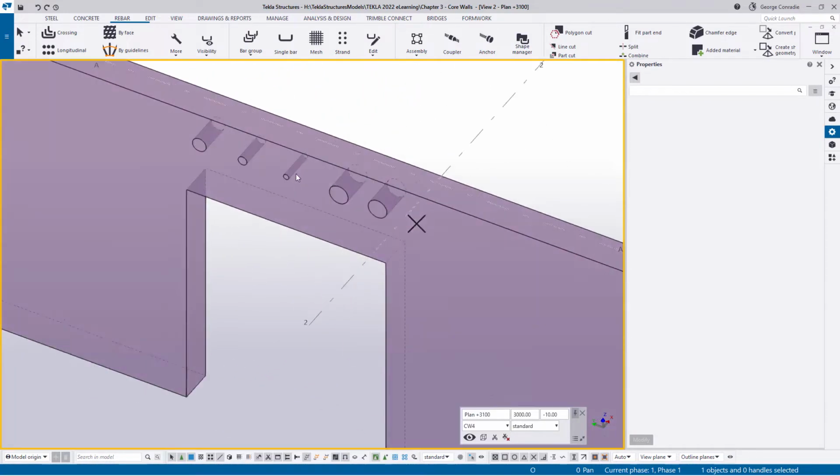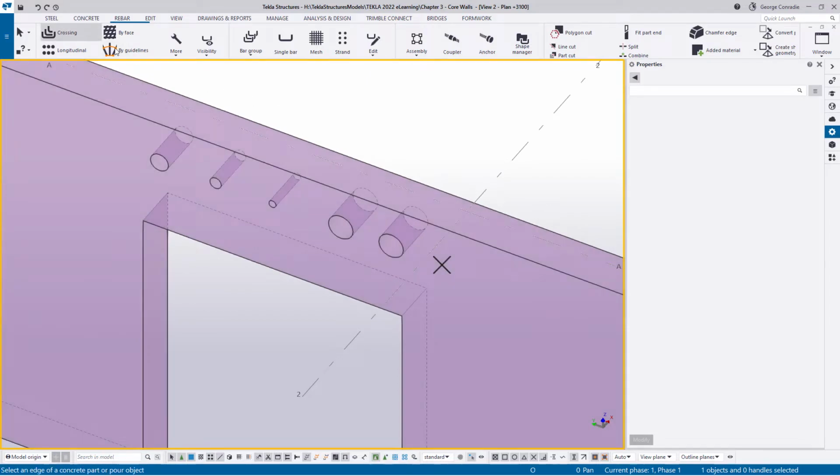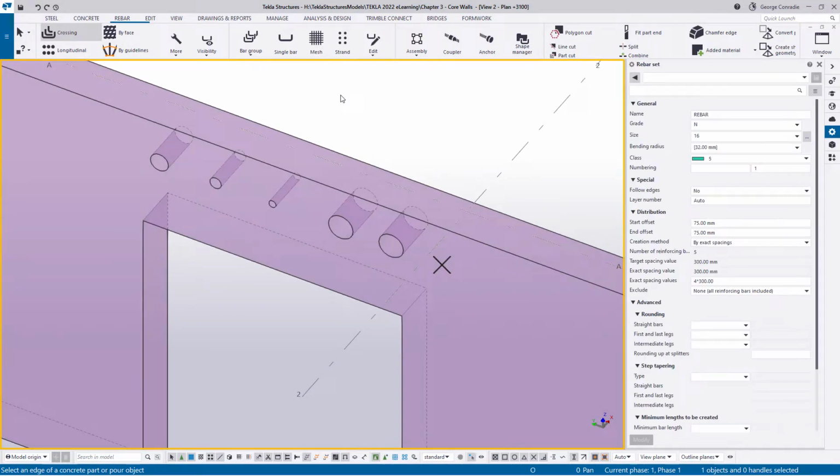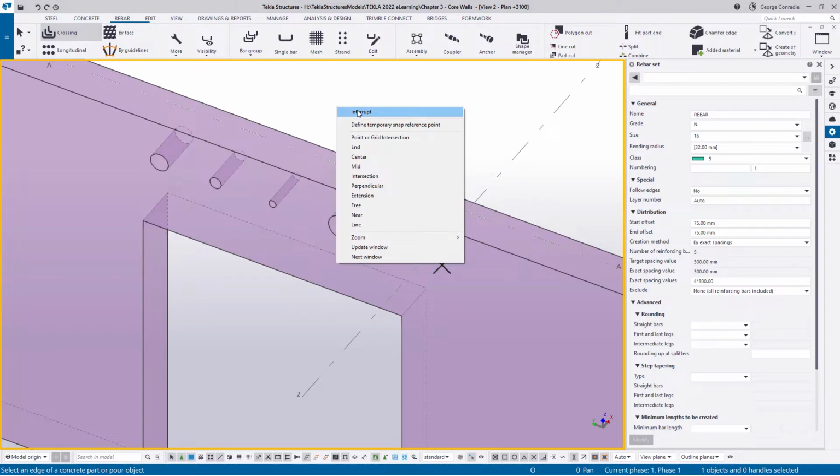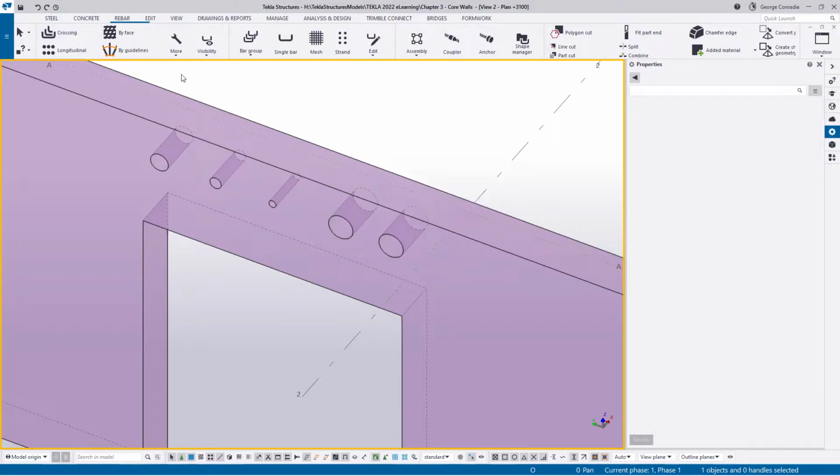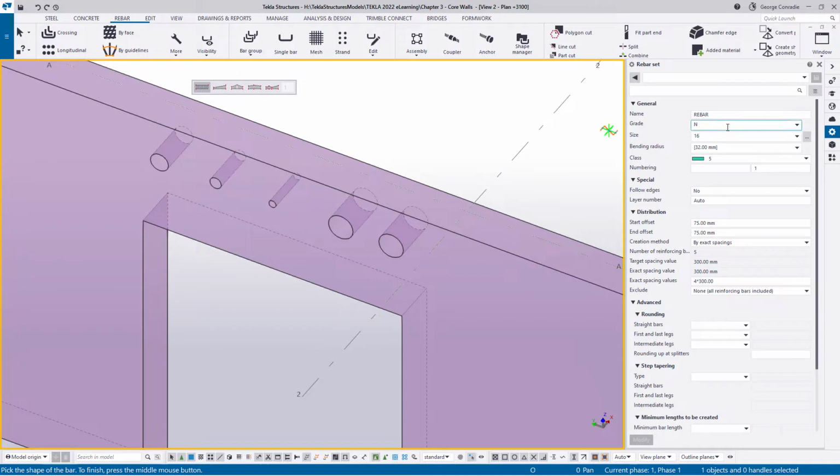Okay, so while we're here, we might as well do these as well. So if I go to crossing bars again, and this time let's do this one a little bit different. For this one, we'll go more point input, make sure it's linear. We've still got our 16s, our same color. We can zero these out, so Tekla auto calculates that, and we'll go by target spacing, and the target spacing is 150. That's just to have an initial value of how many bars.